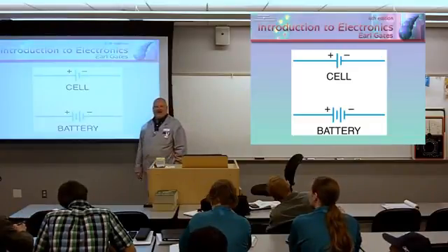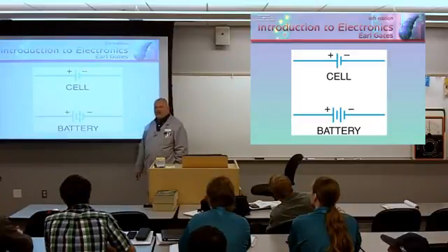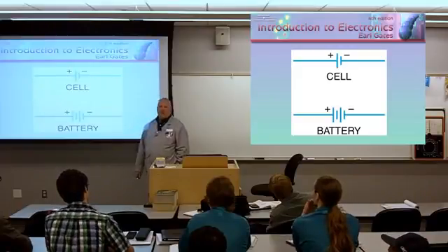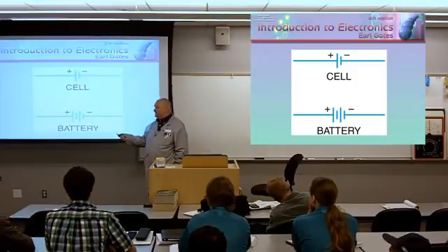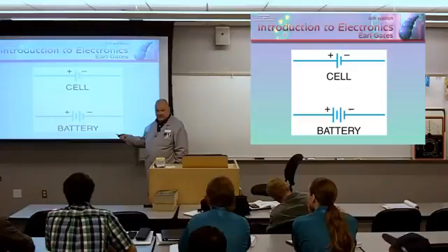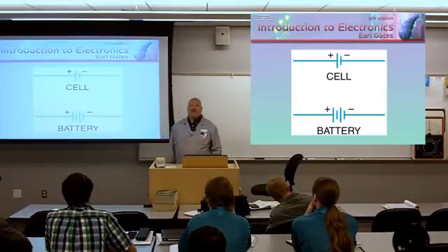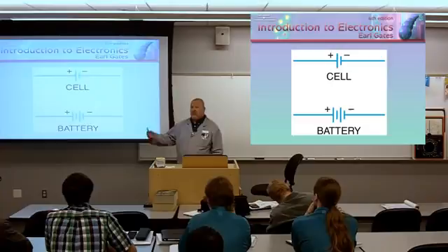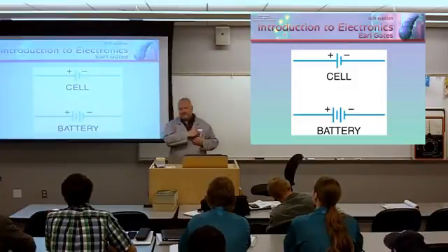So normally on a schematic diagram, sometimes they'll draw 2 of these side by side, sometimes they'll draw 3, but they won't draw any more than 3. So anytime you see 2 or more, assume that it's either the value here, or right next to this I could write 12V. And if I write 12V, well, it's a 12-volt battery pack. And if you split that battery pack open, you would find that it's actually made up of multiple cells that are wired together internal to that battery pack. Make sense?